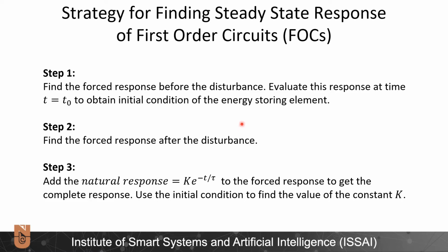Afterwards, we find the forced response of the system after t0, after the disturbance of the circuit, and we add to this the natural response of the circuit, and we use the initial conditions to find the parameters of the natural response.